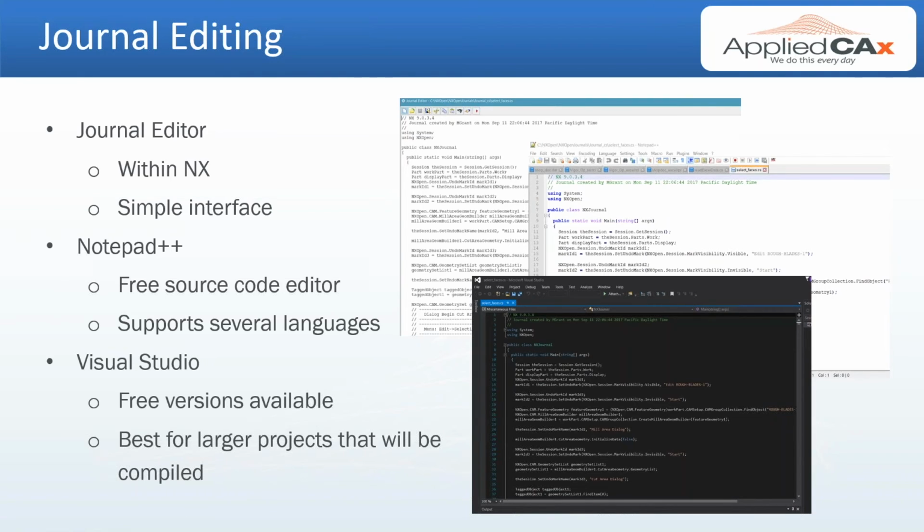And I think there was one more thing that I wanted to say about this. Oh, yes. While NX is backwards compatible, NXOpen is not guaranteed to be backwards compatible. However, it is very rare that an NX routine created for a previous version of NX doesn't work in a later one. The reason is that functions sometimes become deprecated.